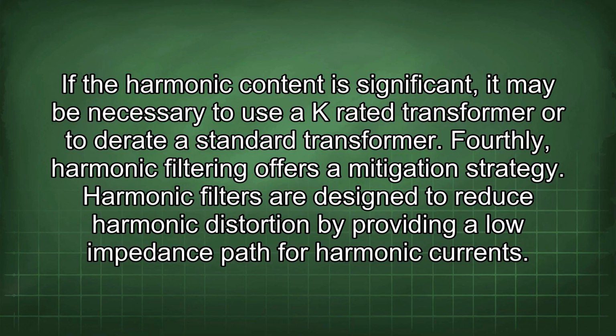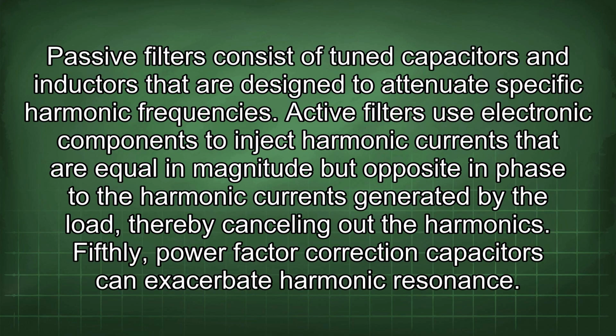Fourthly, harmonic filtering offers a mitigation strategy. Harmonic filters are designed to reduce harmonic distortion by providing a low impedance path for harmonic currents. Passive filters consist of tuned capacitors and inductors that are designed to attenuate specific harmonic frequencies. Active filters use electronic components to inject harmonic currents that are equal in magnitude but opposite in phase to harmonic currents generated by the load, thereby cancelling out the harmonics.